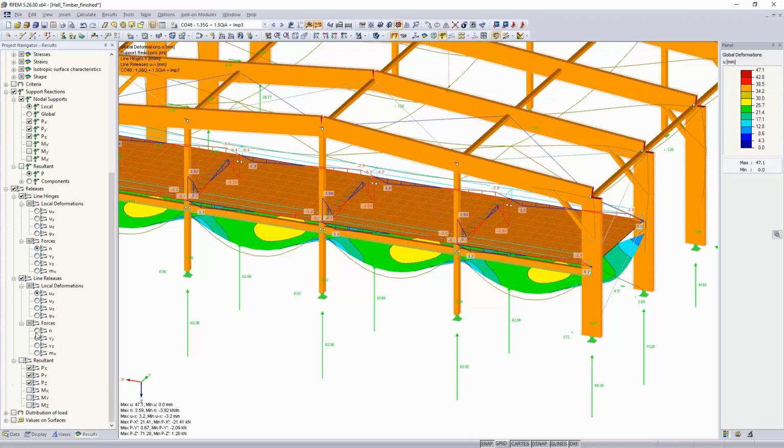but for the plate lying on top of the beam, it's probably relevant, because this is the shear that's in between the plate and the member, and that's what you really need to connect. And you see that there the value is not that low, and that's something you probably need to verify. So this gives you a good graphical overview.